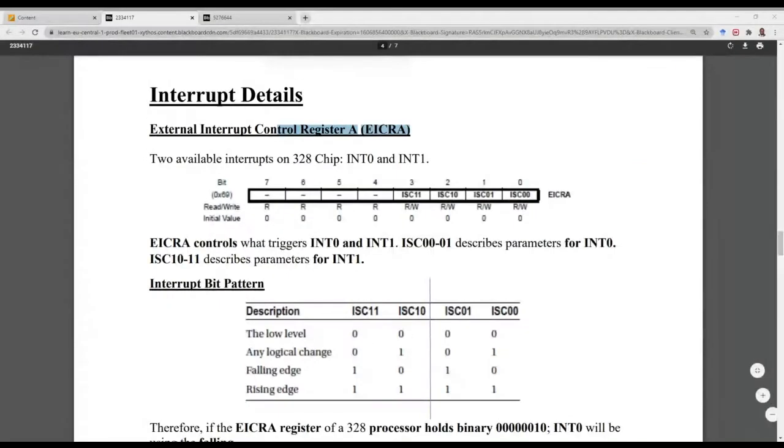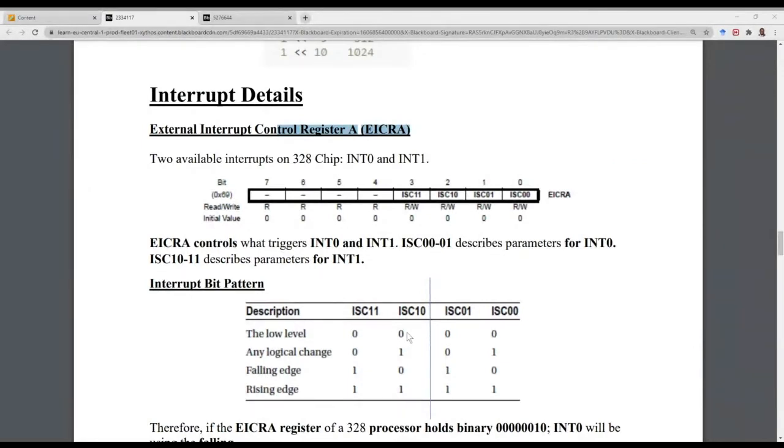Reflecting on the square wave, the external interrupt that we are expecting to happen, when do we want to respond? We can respond if it's at a low level, that is stable state low, or if there is any change at all, or if there's a change on the falling edge, or on the rising edge. So we look for some specific things on the external signal, and this is actually quite good at switch debouncing, or switch bouncing.